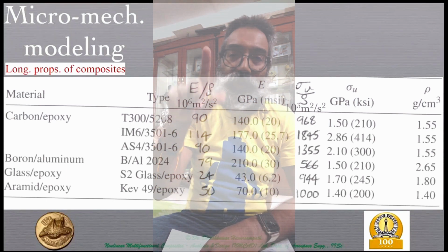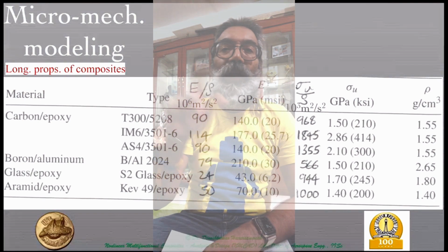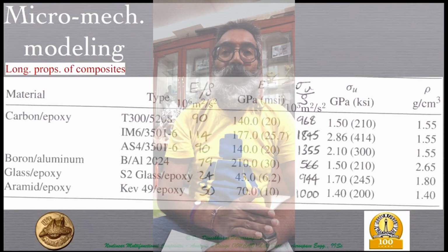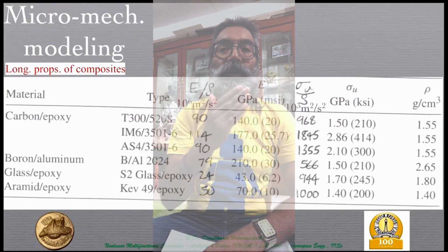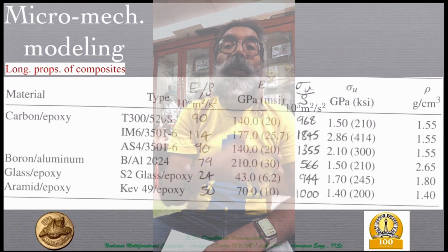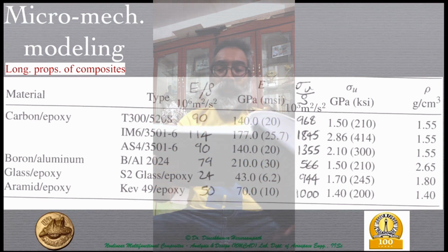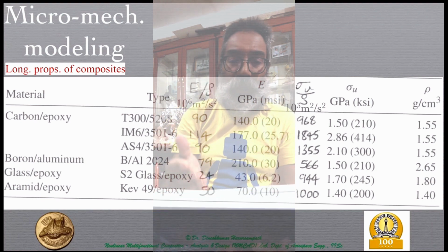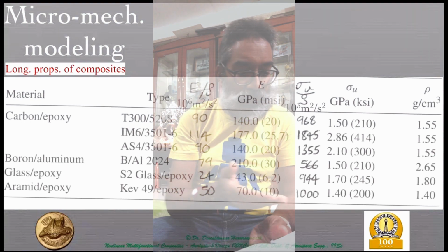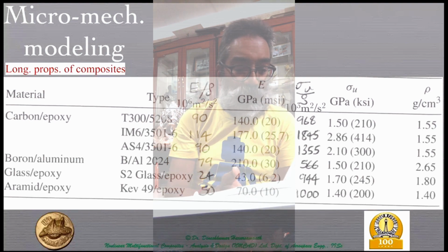So basically the stress, the tensile stress, is changing with time in a cyclic manner, and the number of cycles that it can last in terms of retaining its strength and stiffness is what determines how good it is in fatigue, and 2024 is excellent at doing that. On the other hand, you have the 7075, which has a higher strength, about 538 megapascals instead of 449.